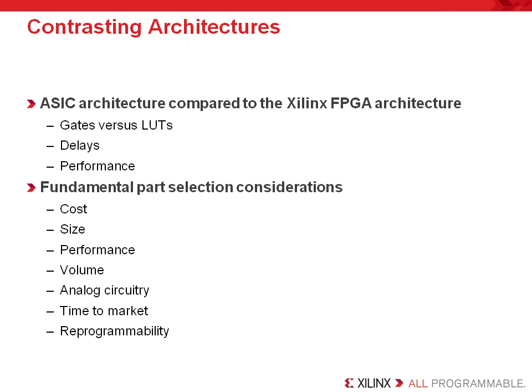As you will see in a few slides, another major difference is configuration. FPGAs are SRAM-based devices, so they need to be reprogrammed upon power up. This requires that customers design a place to store the bit stream of the FPGA in their system. Some customers plan on adding a flash or an SD-RAM component into the system to accommodate this. However, this is not necessary for ASICs. A significant benefit, as you might already know, for configuration is that the FPGA can be reprogrammed many times. This is significant since the user gets plenty of opportunities to fix any design problem they might have.